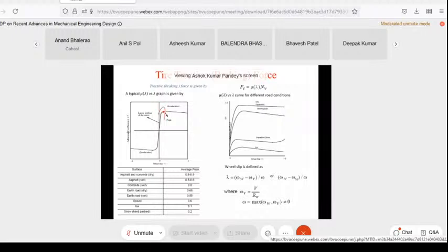The moment it crosses, it means the slope here is positive, and here the slope becomes negative. Means if you try to find out dμ/dλ, μ is your coefficient of adhesion of the tire and road interface, and λ is the speed ratio. So you see that as long as it is positive, your vehicle will be stable, and the moment it becomes negative, it will be an unstable state, right? So that's how things work out mathematically also, if you try to do it.